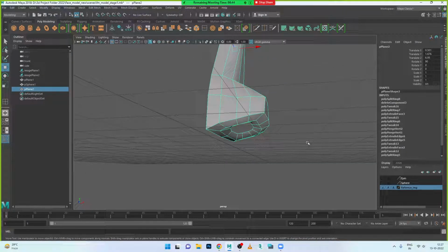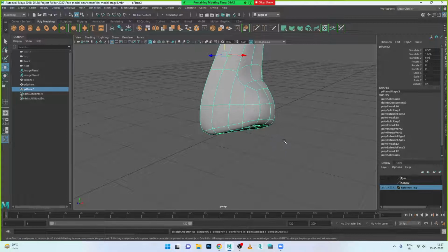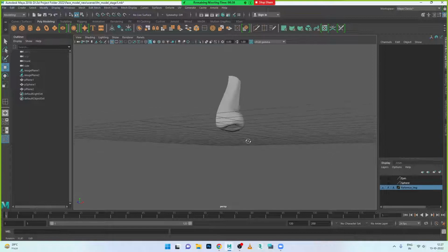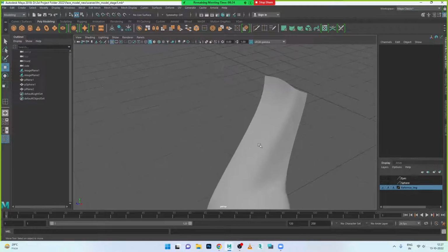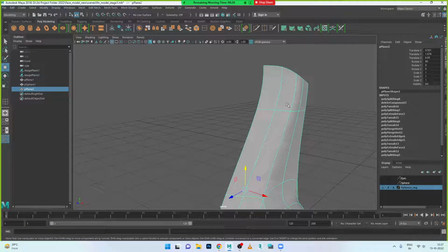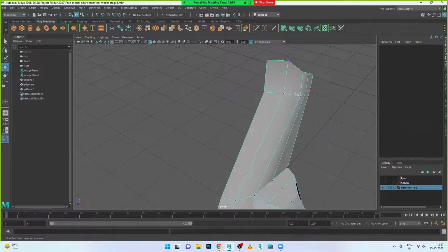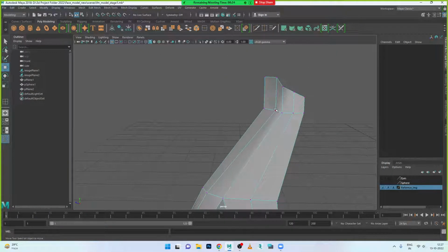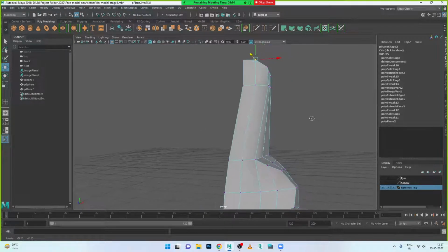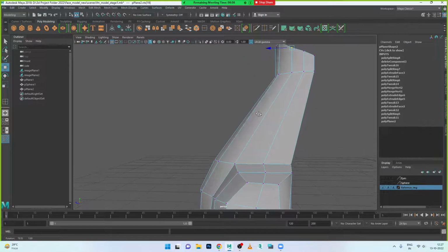Right click, object mode. Okay, press 3 and see once. Okay, now there is some portion with a little sharp edges in this one, we need to balance this here now. Select this one, press 1, vertex mode. Now we can see it is too deep, so move it in front in this one. This one also, it will go front in this one. Now balance and see. Move this one towards left side, this one towards left side, and check from the left side, from the side also if it is perfect or not.